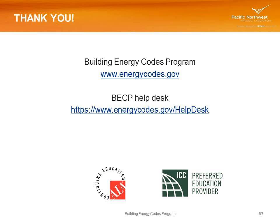So if you're doing dehumidification control, there are requirements that you have either a space sensor or an outside air sensor on the humidity side that only takes that action or that override when it's necessary for humidity control, not 24/7 all the time.